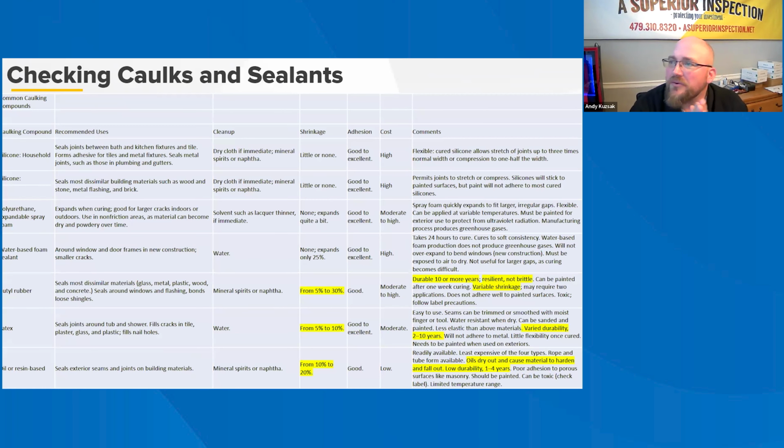In the construction of a weather-resistant envelope, a WRE system, there will be joints and seams that require or at least benefit from the appropriate use and maintenance of caulks and sealants. In the absence of guidelines for specification and application of caulks and sealants in model building codes, this section provides valuable information for inspectors regarding their use. Where caulk is required by manufacturer's installation instructions, the specified caulk materials and methods should be followed carefully by the installer and then checked by the inspector. In general, caulks and sealants should not be relied on as the primary defense against water intrusion at joints in WRE systems. Flashing is preferred where feasible, even when caulk is additionally used.